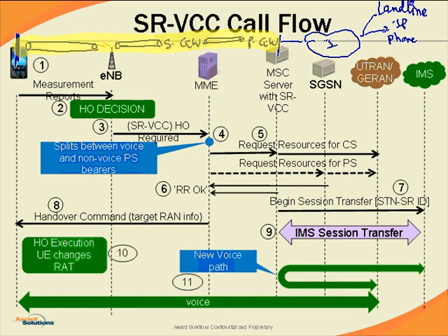Yeah. That's a very good point about codecs. We have voice over LTE recommending, actually requiring, the AMR speech codec. But in 1X we would be using EVRC. So we would have basically our device with multiple codecs. So when we are on LTE, we will use the AMR speech codec.